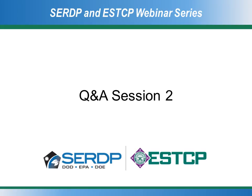Yes. For an amendment injection, what conductivity contrast do you consider reasonable to image with ERT? So the higher the contrast, the better, but I would say at least a factor of 10 conductivity contrast between your existing groundwater fluid and what you are injecting. So if you don't have that type of contrast, you can always spike your amendment with some type of conductive additives such as sodium bromide or calcium chloride, calcium bromide. Great, thank you. A question from the EPA.